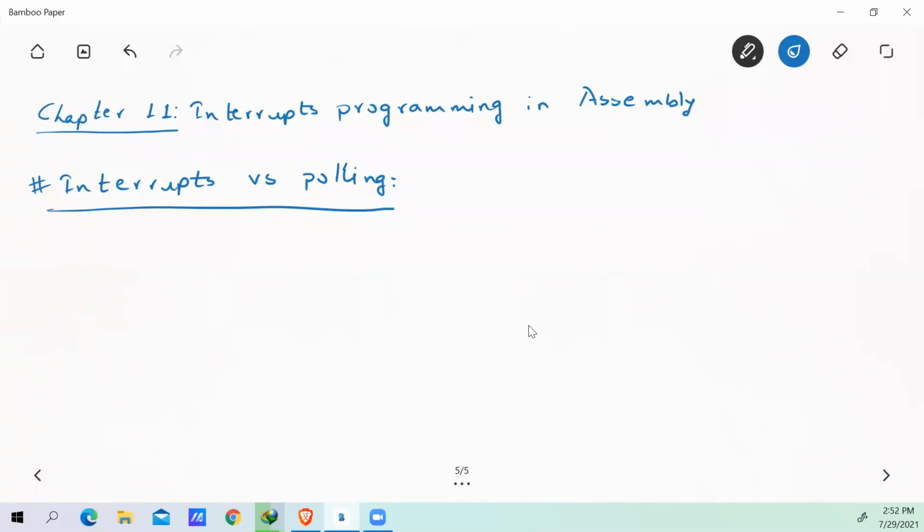Let's see, the advantage of interrupt is that, we say the microcontroller will poll, which means it will check the status of a device continuously for a specific period of time, then go to the next device. In this way it will keep on going. Say you have given some task to device 1 and you have set it so that whenever it finishes the task, the microcontroller will need to do something.